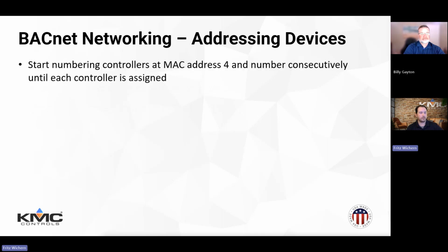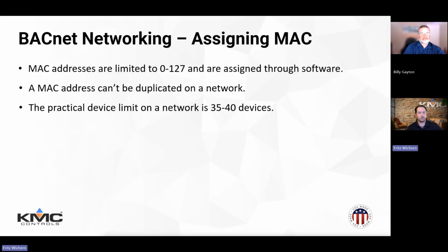I'm sure we've all run into situations with duplicated MAC addresses, and the joy of going through and figuring that out. The practical device limit is 35 to 40 devices, but it depends on network load and network speed.